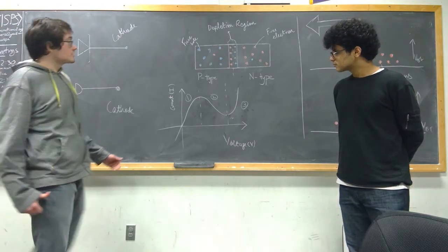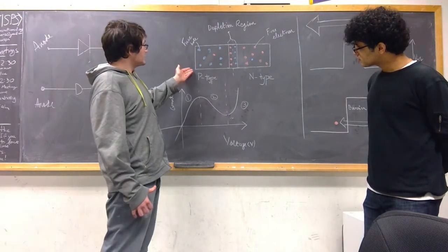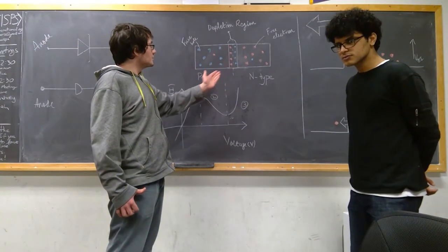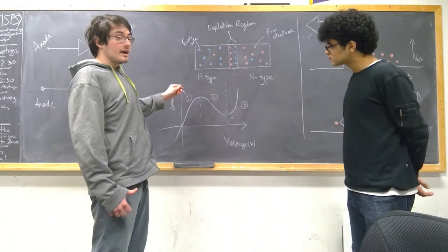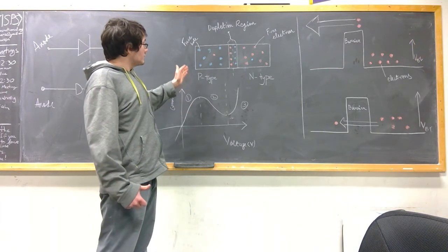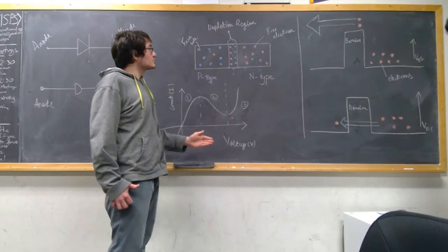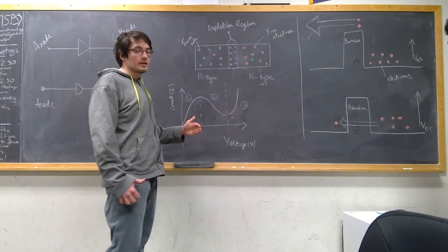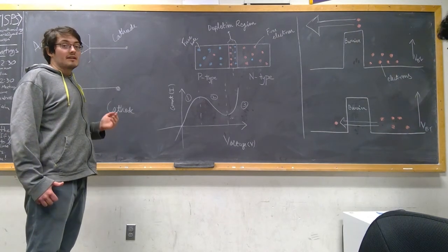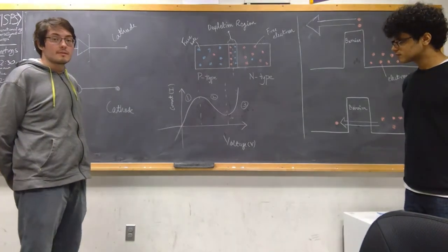Diodes are semiconductor structures made up of a p-type region and an n-type region. When a positive voltage is applied between these two regions, strong enough to overcome the barrier potential caused by the depletion region, current can flow through. Tunneling diodes are a heavily doped variant of the normal diode, where at incredibly low applied forward voltages, electrons can instead simply tunnel through the barrier potential rather than requiring enough energy to go over it. This allows tunneling diodes to be used in low voltage circuits and incredibly high frequency circuits due to their incredibly fast switching speeds. Thank you for listening.